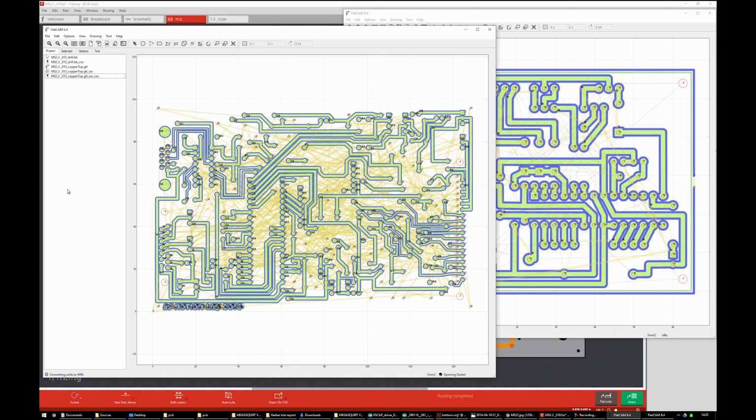So one thing that happens is the bottom layer is obviously loaded in the same position and the same rotation and orientation as it came out of Fritzing, which is basically the two layers are overlaid over the top of each other. But if you think about this, the CNC machine doesn't cut both layers from the bottom and the top. You need to flip the PCB to do the bottom. So you need to do that in the file. You need to reflect that.